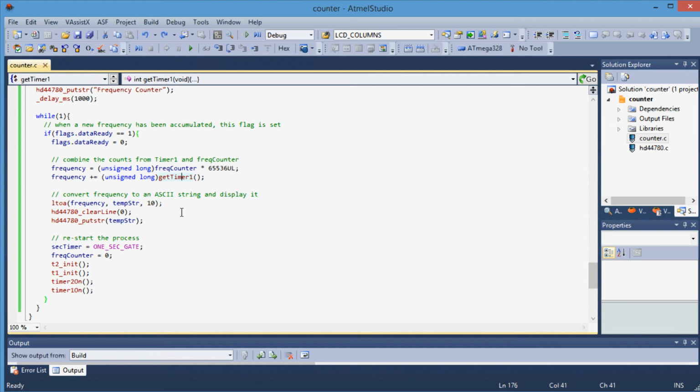So you can measure frequencies using the same method here, but using a Microchip PIC controller, up to 50 megahertz. In fact, that little homemade frequency counter that I showed you on my workbench at the beginning of this video is using a Microchip PIC controller. I've had that counter counting as high as above 30 megahertz, and it works reliably at that frequency. Anyways, we're using an Atmel part which has that limitation, but if you don't need to go above 8 megahertz, this thing works just fine. It's a good part on its own as well.